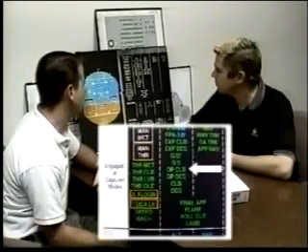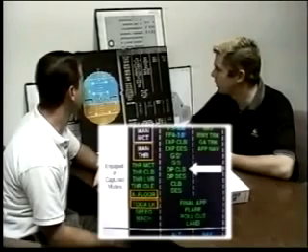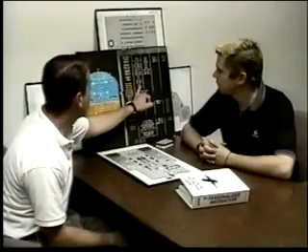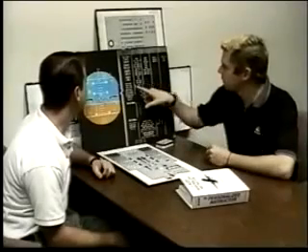About open climb. Thrust climb, open climb. Open climb is only done at climb thrust, so it's thrust climb. Open descent? Thrust idle, open descent. Open descent is only done in an idle thrust, so it's thrust idle. What about VNAV climb or your climb FMA? Climb is the same thing as open climb for us, so it's going to be thrust climb. Regardless of whether or not you're using the FCU properly, the climb mode will be at climb thrust.